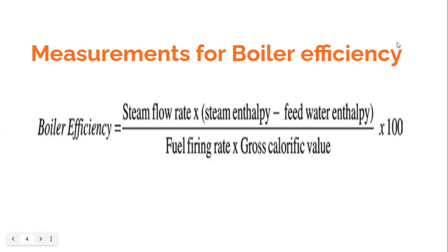That is because in the industry, in certain countries, you would find that the boiler efficiencies are expressed on the GCV basis, and in some other countries, you would find that they are expressed on the NCV basis. So if you want to compare two efficiencies, then it is better to compare apples with apples than apples with mangoes.